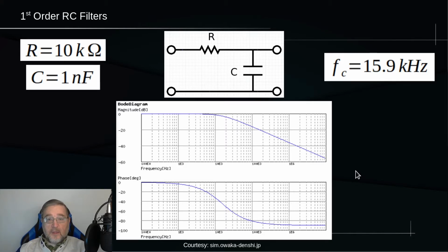Remember what we saw in lab? When we were injecting an input signal with a very low frequency, input and output signals were perfectly in phase. But then, once the frequency grew higher, we started seeing a shift of the output signal with respect to the input, and at the cutoff frequency, the shift was 45 degrees, while at the very high frequencies it was 90 degrees. Well, this phase diagram provides the graphical representation of what we saw, and all the numbers have a negative value that represents the direction of the temporal shift introduced by the capacitor.